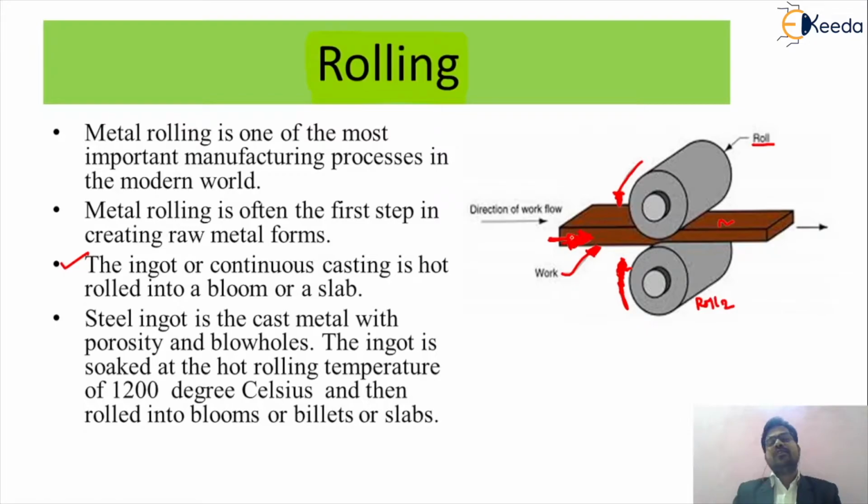As shown in the figure, friends, to understand the detailed process of the steel rolling mill, we have to get one type of ingot. And what do we mean by the ingot? It is simply a continuous casting of that metal piece, and we roll that cast material through blooms or slabs, by which we get a finished product of steel sheets, steel bends or steel structures. So this is the actual process carried out in different types of steel rolling mills.